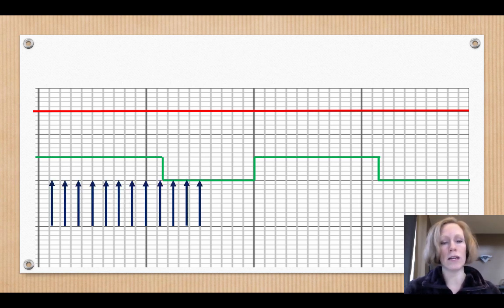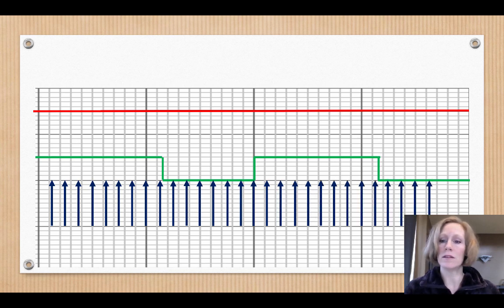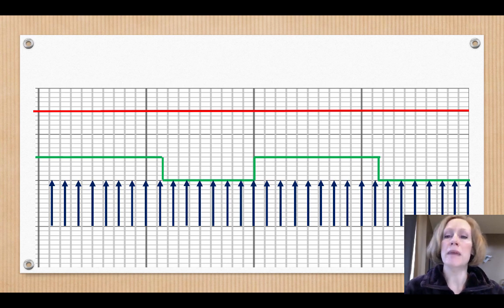The arrows are indicating a command each time it runs the loop for the light to turn on. You can see that in some parts of the loop the light turns on and it's red and green, and in some parts of the loop the light turns on and it's just red. So we can see this kind of flickering happening. What we want to do is make this PWM wave faster than how fast the loop runs, so we can play with the timing of it.